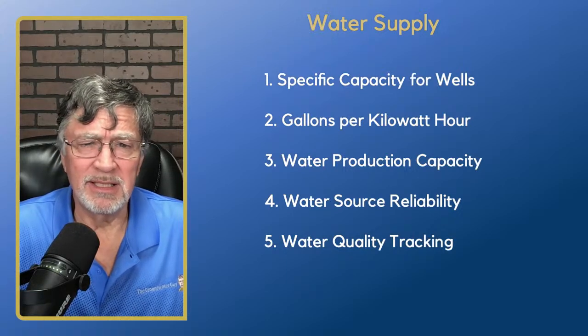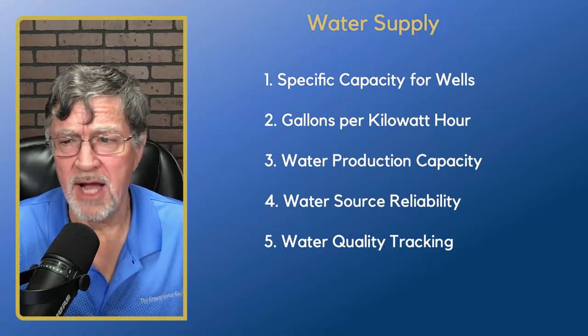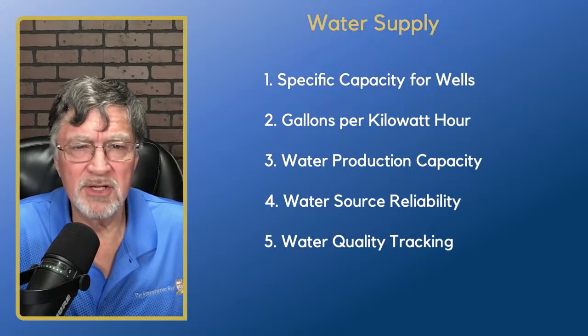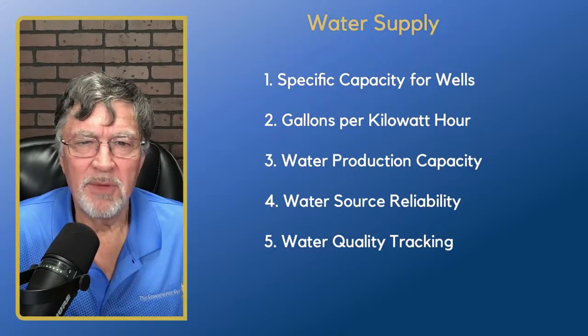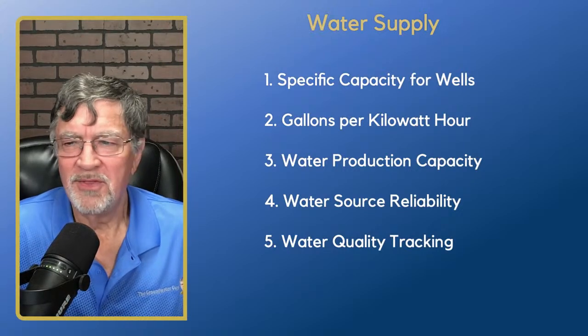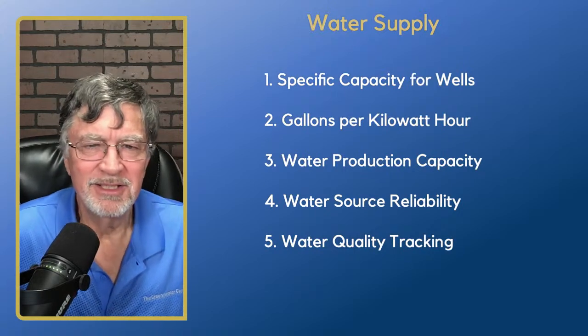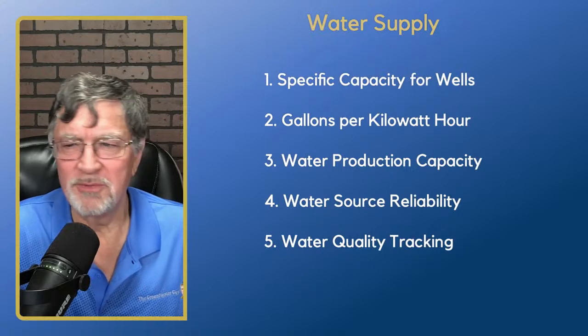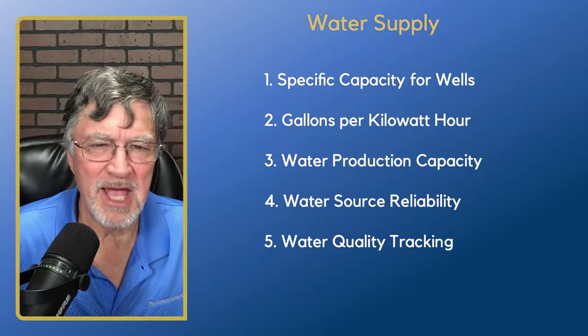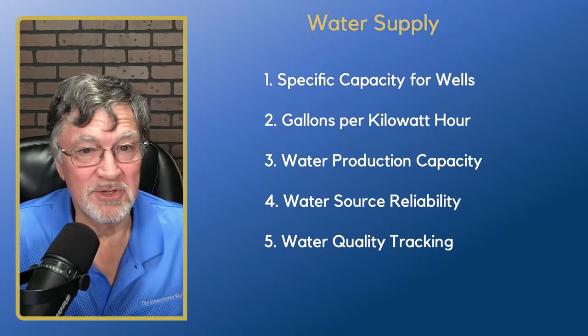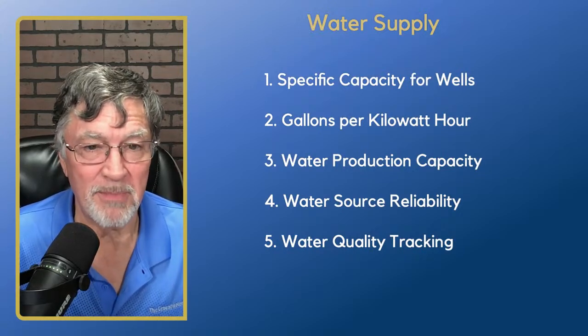But what actually is going to be our maximum daily production capacity? And if that is going down, then there may be a point where the maximum daily production capacity that you're tracking meets or falls below the maximum daily demand. And if we see that trend happening, then we really need to seriously look at developing additional capacity.